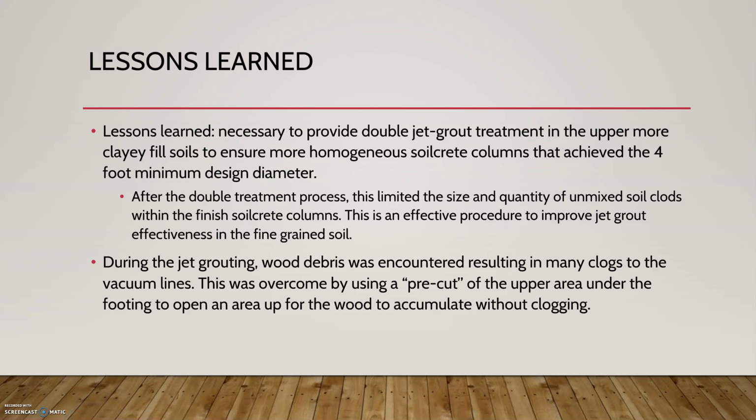So during the jet grouting process, we also found some wood debris was encountered, resulting in many clogs of the vacuum lines. To overcome this problem, they created a pre-cut of the upper area of the footing to open up an area where the wood could accumulate without clogging.